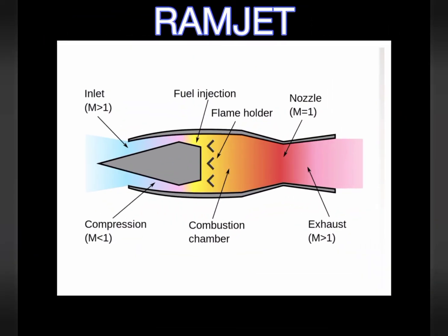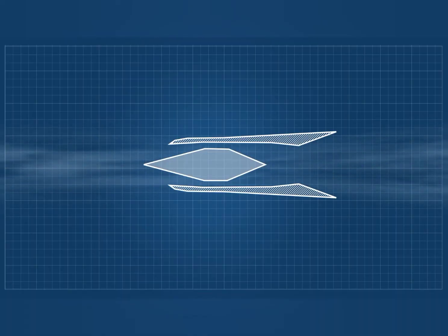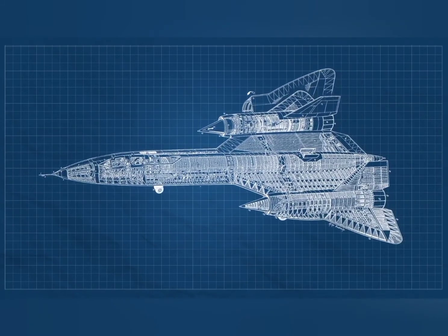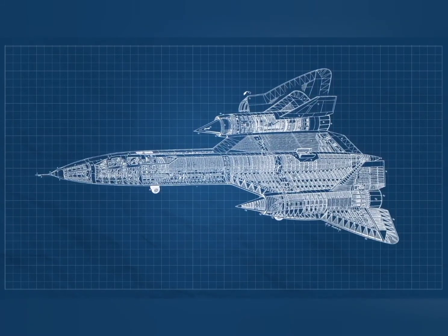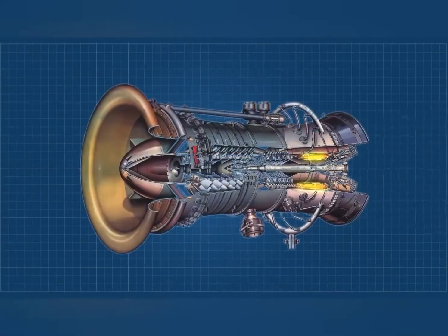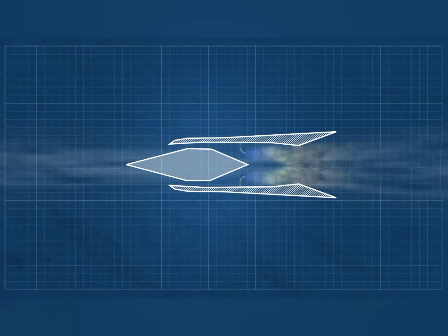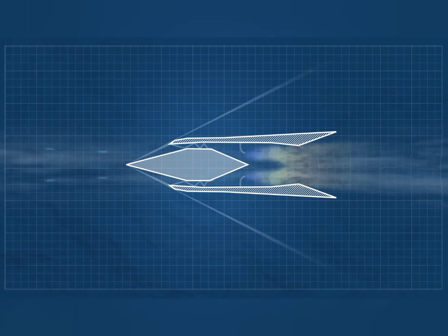Ramjets are the lightest types of engines in aircraft and come with no moving components. The speed of an aircraft is responsible for forcing air into the engine. Ramjet operates the same as a turbojet, except that the rotating parts are not present. However, the fact that the compression ratio depends on the speed of an aircraft restricts the application of ramjet engines.